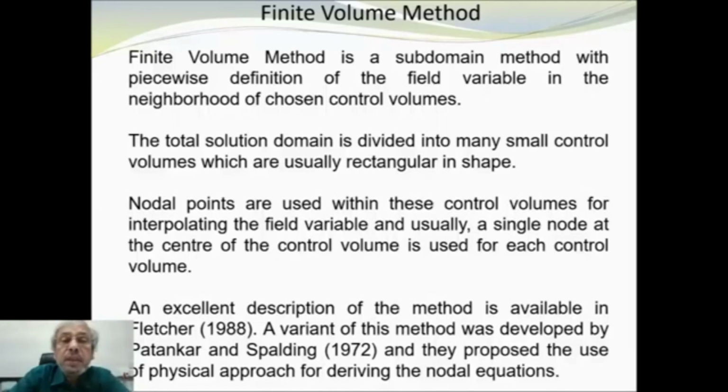Finite volume method is a subdomain method with piecewise definition of the field variable in the neighborhood of chosen control volumes. The total solution domain is divided into small control volumes, which are usually rectangular in shape. This may not be exactly rectangular, we'll see later.